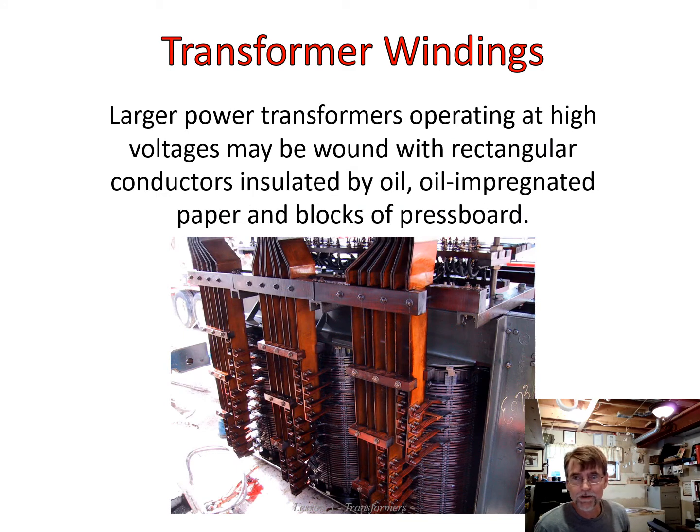Larger power transformers operating at much higher voltages, they may be wound with rectangular conductors insulated by oil-impregnated paper and blocks of press board. So it's a considerably more complicated arrangement. Okay, we've got to make sure at high voltages that we can't defeat the insulation.